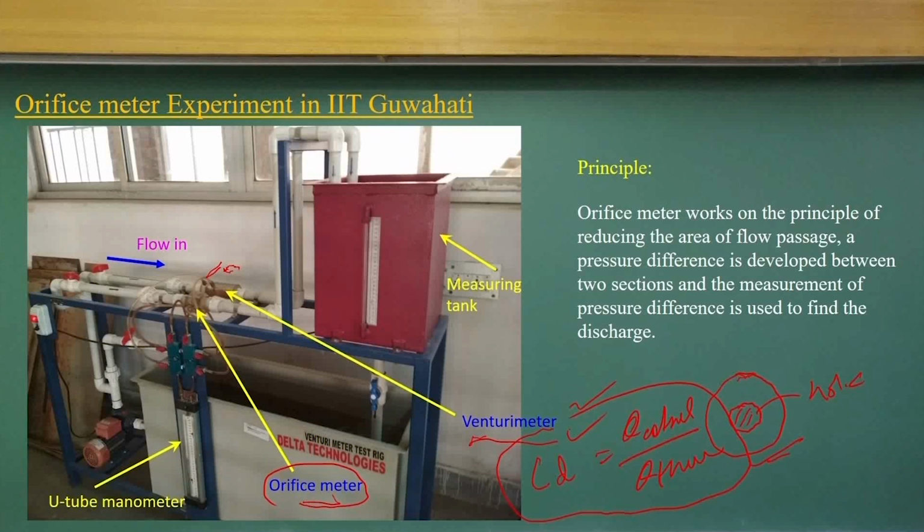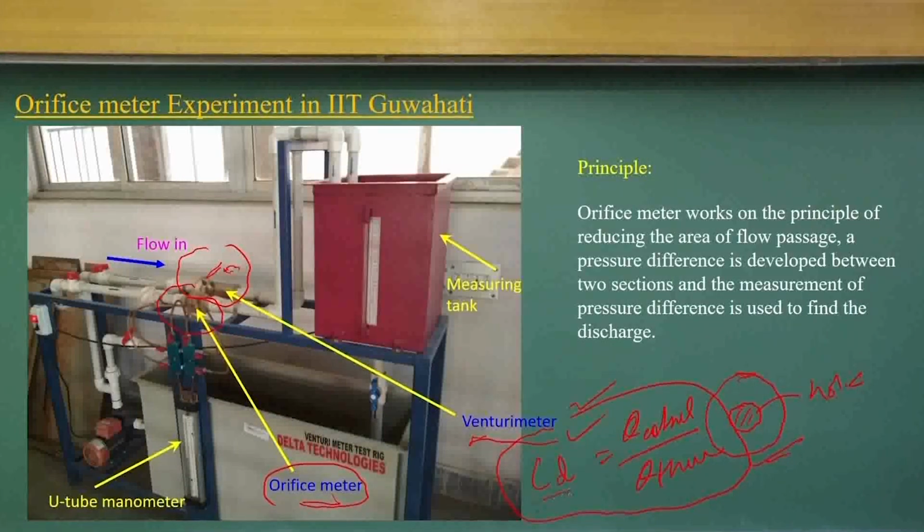Now, if you try to understand, many times we do not go inside these fluid flow problems within the venturi meters or orifice meters, to see how the flow streamlines happen and how the energy dissipation happens. We do not look at that in depth, but in terms of these flow patterns, the gross characteristics in terms of energy losses and reductions in discharge, that is what we introduce as the CD coefficient, the coefficient of discharge.